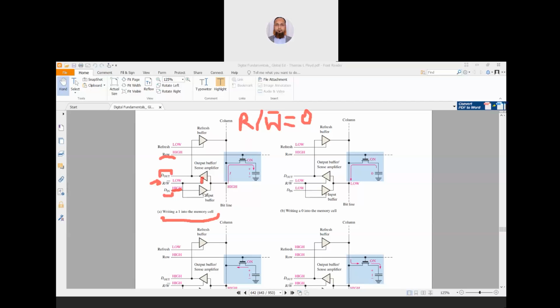This is low, and this low is connected here as 0, and there is an inverter here, so the output of this inverter will be 1. It means the 1 will be applied to this buffer, and the buffer will be enabled. So this input buffer will be enabled. Whatever high data is applied here will be available at the output. A buffer transfers the same data, it is not an inverter. Whatever data is at the input, it transfers to the output. The only thing is that they are used for impedance transfer, to avoid the loading effect, as you might have studied somewhere.